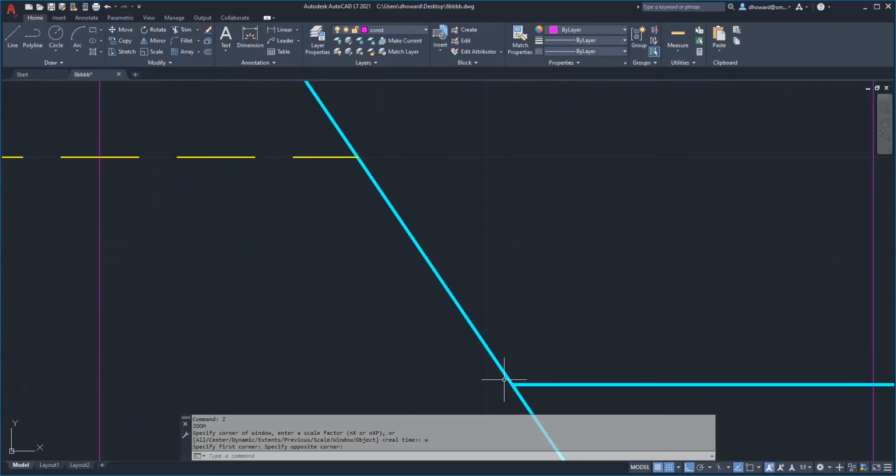So when you go to draw those vertical construction lines, if you have the grid snap on like I do, you can see it's not going to snap to the right point. It's going to be a little off. You can see both of those are off. So you have to place those with your grid snap off and your object snap on.